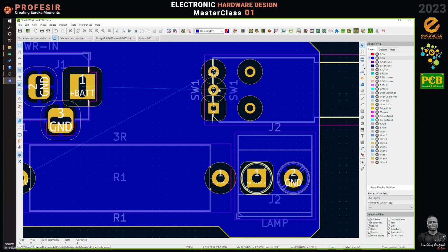The 12 volts would have to cross over it. We will route the battery through here, but the 12 volts would have to cross. Technically we can pass that here and route it, but I don't like it. Now, looking at the nature of this connector, this is not what we plan to use. But let's assume for a moment we can use any of these pins. It means I can rather connect my 12 volts here for easy routing.